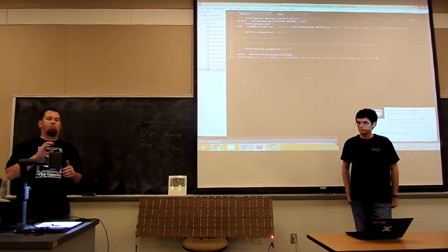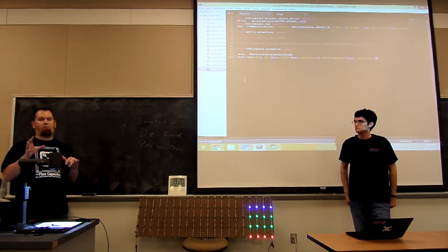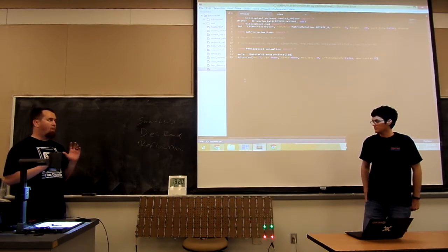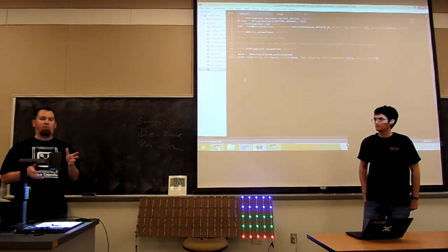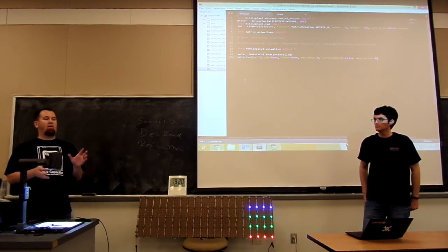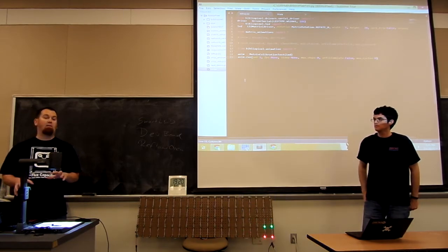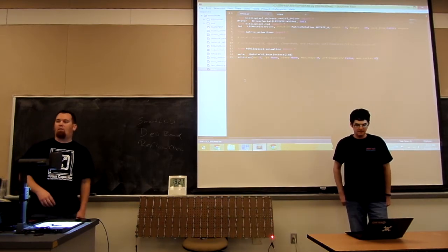There's a full segment of color classes that allow you to do HSV color, both with the standard 0 to 359 or 360 setup, but also a modified one, which is a byte-based HSV, which is about 6 times faster. It's not quite true to the normal HSV color space, but I've rewritten the entire thing for speed. So a lot of times it's close enough for what you need, but you can do it either way.